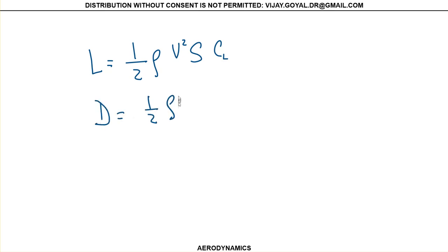Okay, so with those ideas fixed, we can now go back a little bit and redefine our function, your lift. That was the density, velocity, surface area of my wing, or span area, times CL. D is equal to 1/2 rho v squared S CD. This is the coefficient of drag. This is the coefficient of lift.